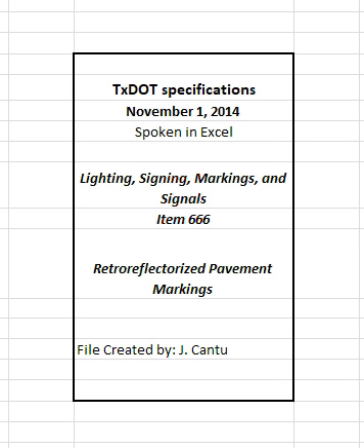4.2.2 Cleaning for old asphalt and concrete surfaces, excludes retracing. Clean old asphalt surfaces more than 3 years old, and all concrete surfaces in accordance with Item 678, Pavement Surface Preparation for Markings, to remove curing membrane, dirt, grease, loose and flaking existing construction markings, and other forms of contamination.